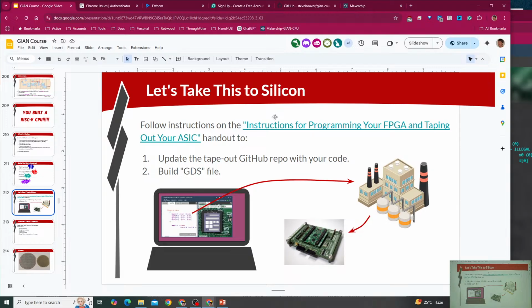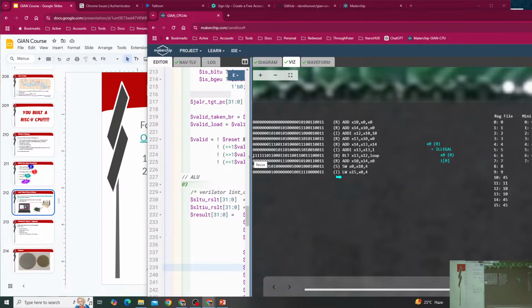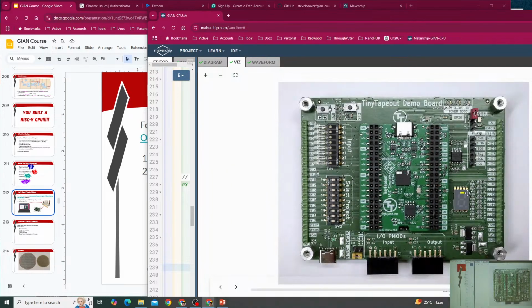But the CPU, fortunately, is entirely driven by your program. So there's no special hookup for inputs for the CPU. If you were working in the template as intended, we can verify this in this visualization. So there's no inputs to worry about. That's all embedded in the memory. The output, our CPU has the passed and failed signal that we use to communicate with Microchip, so those should be hooked up to the outputs of the FPGA.